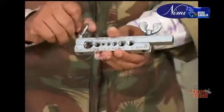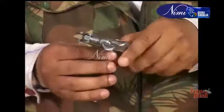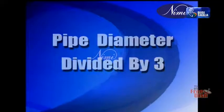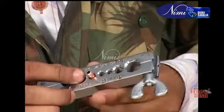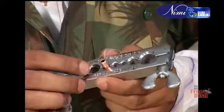Choose the correct size of hole and place the pipe properly. Tighten on the flaring bar hole. The height above the block is pipe diameter divided by 3. If the pipe is quarter inch, that is 6 millimeter, position the pipe so that the end is at least 2 millimeter above the top of the flaring block.